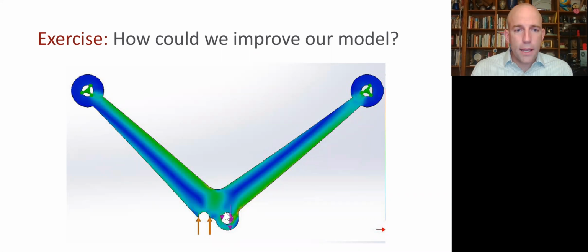And that means that half the force will be on the top of the hole and half will be on the bottom. And so in the real system, all the force will be on the bottom. And so this small lower section of material will experience twice the load as what's simulated here. And so our prototype test is pointing us to a way to improve our finite element analysis in this case.